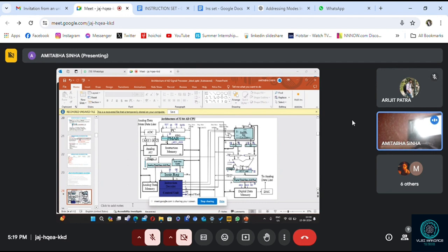Now, what is it capable of doing? An operational amplifier can do addition and multiplications. There are two types of multiplications. One is constant coefficient multiplication, and another is multiplying two time domain functions. For example, let's say Em sine omega t.